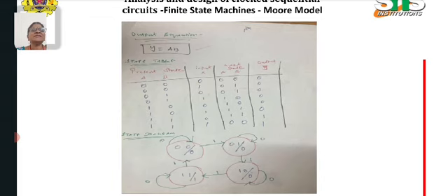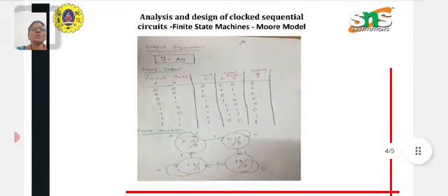The next state is derived by using the input equations and the output equation to build the truth table. Whatever equations we have written there should be the same here in the truth table. The output equation is y is equal to AB. So here your inputs are 0, A is 0 and your next state A is also 0. When you multiply A into B, you get the output Y. This is how I have derived the truth table of this Moore circuit.